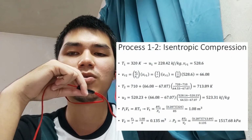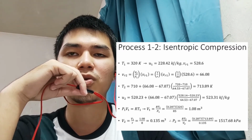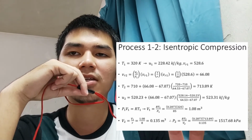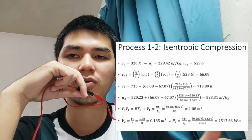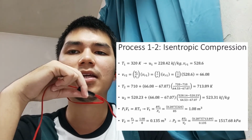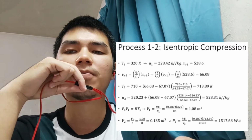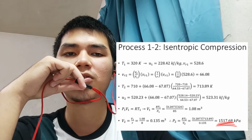For the first process, 1 to 2, the isentropic compression, T1 is 320 Kelvin, right? So we need to find the internal energy and the VR1, where we use the ratio to get VR2, which is 66.08. Next, we need to calculate temperature 2 and internal energy 2 by using interpolation from the steam table, and we get 713.89 Kelvin and 523.31 kilojoule per kilogram. For the pressure, we get pressure 2 as 1517.68 kilopascal.